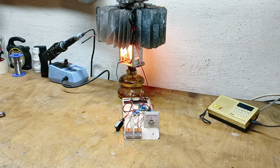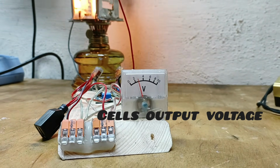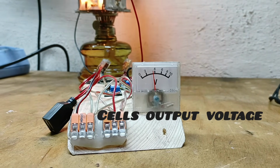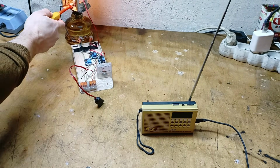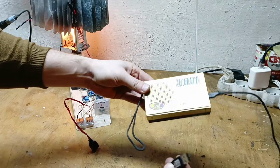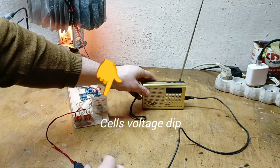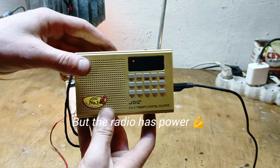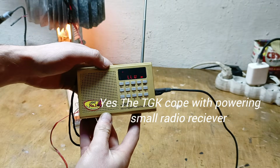So all three converters were set to output 5.5 volts, which is a suitable voltage level for powering a small FM radio and of course charging a phone. That's why the output of the entire circuit includes a cable with a USB port. Okay, now it's time to see if a generator built this way can actually be useful. First, I will try powering a small FM radio. After all, as you may remember, that's exactly what the original TGK thermogenerator was intended for, powering radio receivers in the non-electrified territories of the Soviet Union.